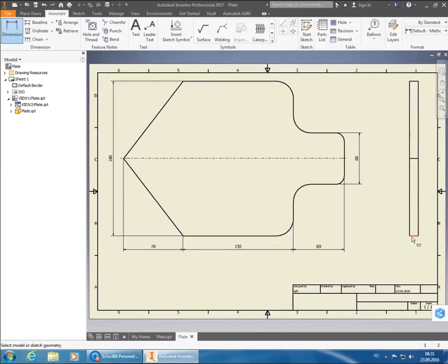And then I try to position my mouse pointer so that I don't get any green dots there, that I'm just marking the line itself as red. So when I click the line, I get just the thickness of the line there. And again, I want it actually to be in line with these dimensions. So I do the same here.